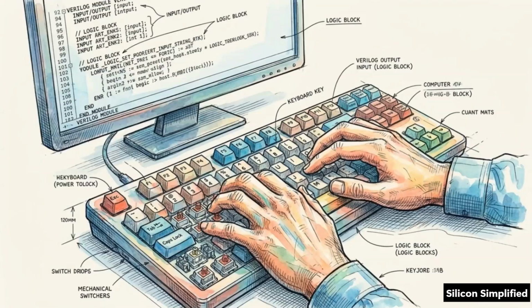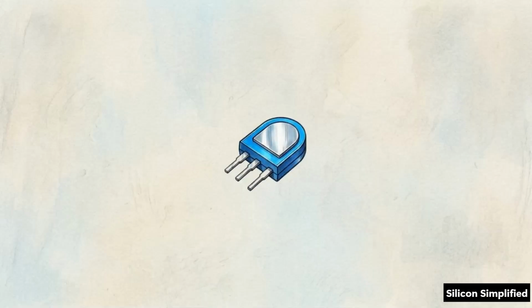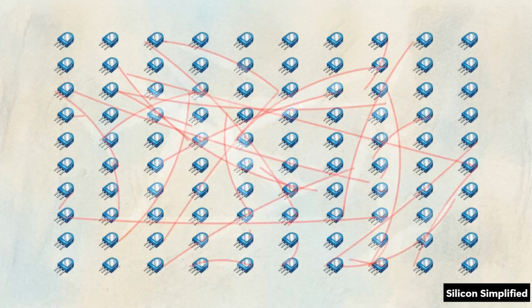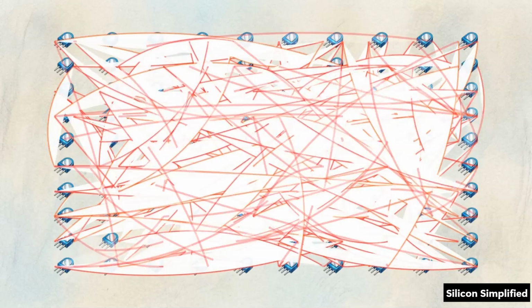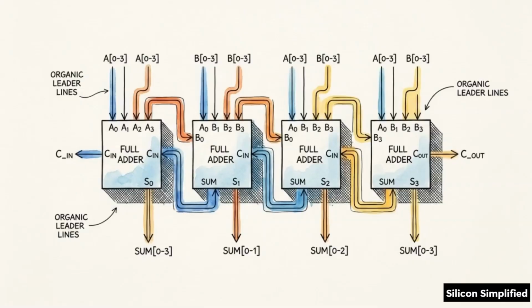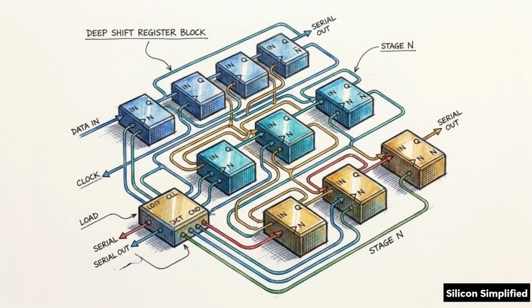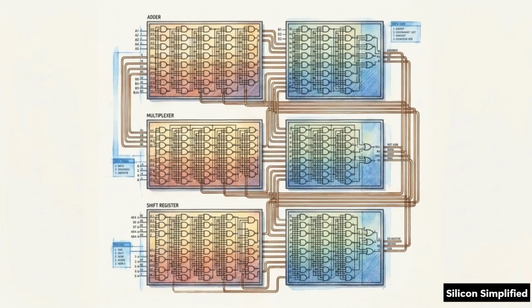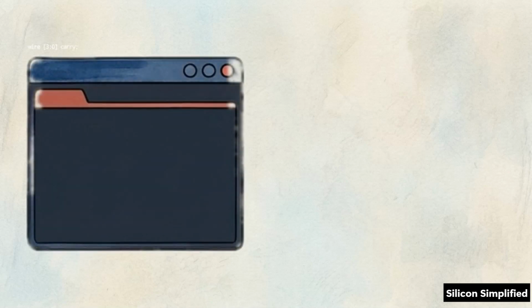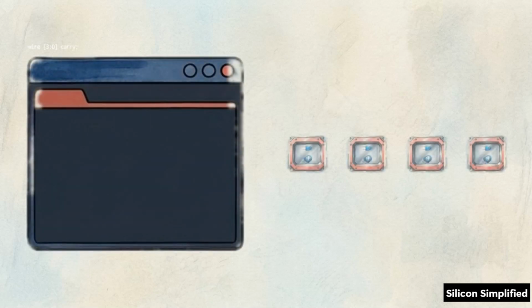In digital design, building structural RTL requires the manual declaration and connection of every physical component. When a circuit demands an array of identical primitives, that manual wiring becomes a significant bottleneck. It's visible in ripple carry adders, wide data path multiplexers, or deep shift registers. Take 4 separate instantiations of a full adder module, mapping the input and output ports of each one by hand.